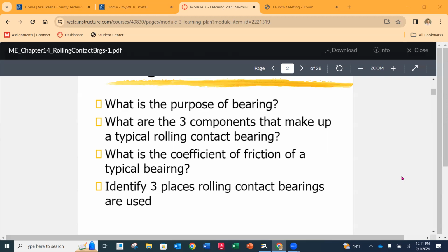It can be supportive, right? So what's a typical place that we see bearings used as supports? Right. Yeah. Wheel bearings on a car. Where else? Shafts, crankshafts in an engine, any type of shaft. Usually a shaft is going to spin, right? Most often it doesn't have to, but then we need supports in different locations, and having a bearing there to allow that to freely move relative to whatever the element is with minimal friction or least resistance is really important. Good. Any other thoughts about purpose?